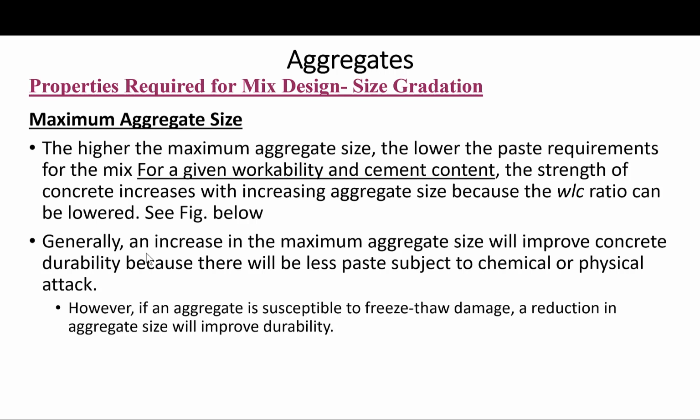For concretes with low cement contents, which are typical of mass concrete, they show a continuing increase in strength with the increase in size. These are low cement content mixes. Generally though, an increase in the maximum aggregate size will improve concrete durability because there will be less paste.